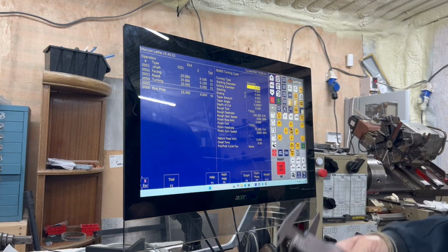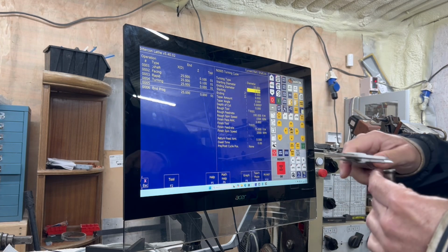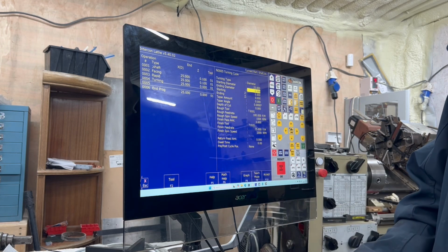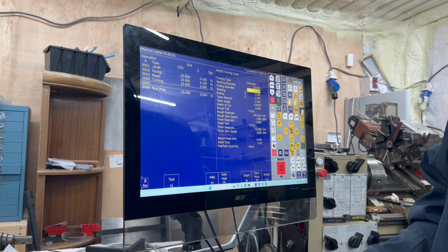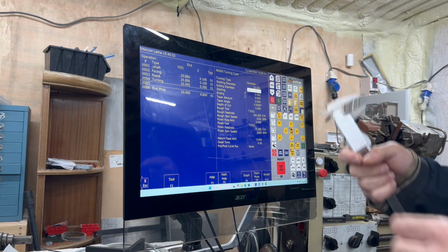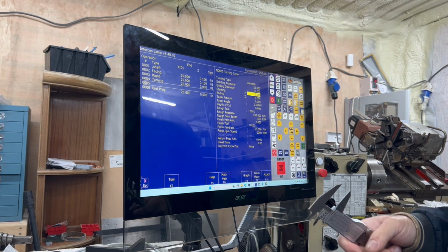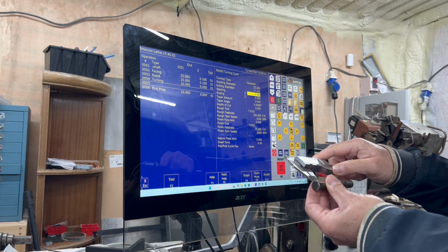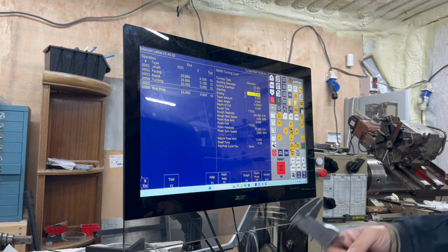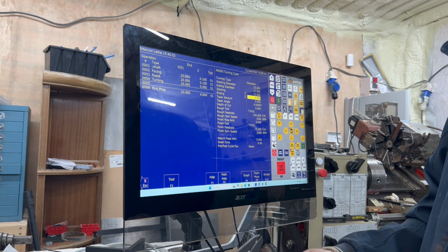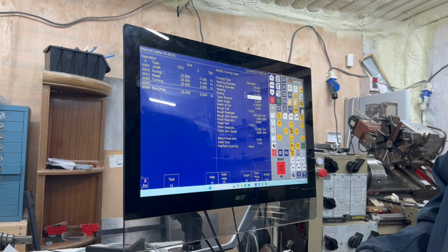The stock diameter, if you remember, is 25, and I want to end at, this looks like about 16. So I'll put 17 here, because the diameter actually doesn't really matter. It's the shaft that the stub just holds on the far side. Now if you remember correctly, we went to 72, so I need to start at 72 and end about 3.5 mil later. So I'll start at negative 72 and I will end at negative 75.5.